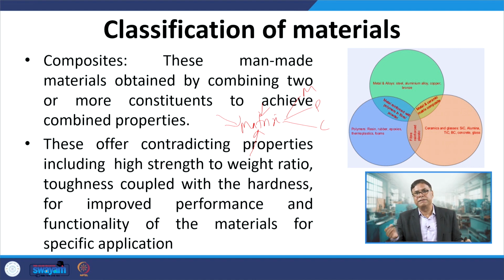Say for increasing the wear resistance we introduce hard constituents. For increasing the electrical conductivity, we introduce particles which have good electrical conductivity like graphite powders. For increasing the lubrication characteristics, we try to introduce molybdenum sulfide or graphite in the metallic matrix.